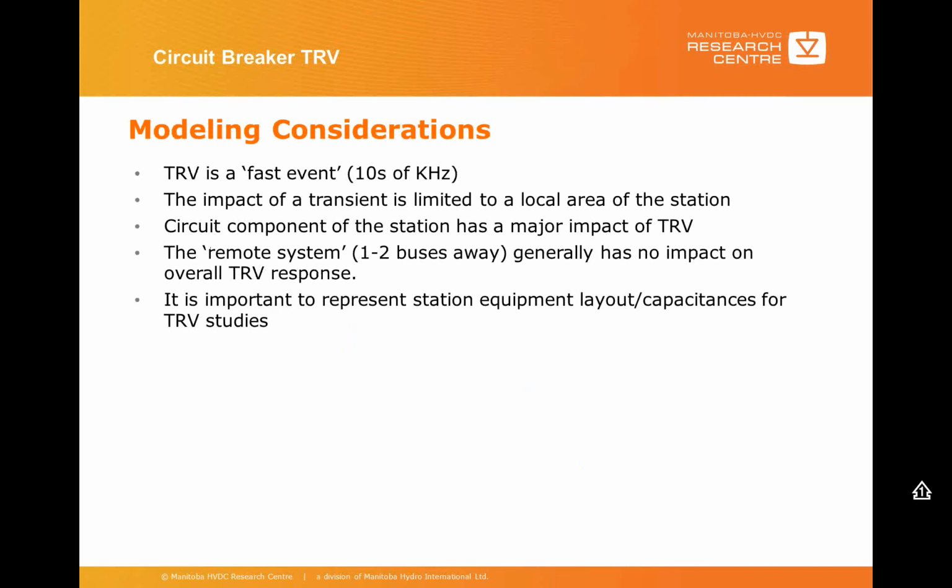Next, we will talk about modeling considerations in PSCAD once you want to do a TRV study. As you know, the TRV consists of fast events in the tens of kilohertz. So the impact of this transient is very limited to the local area around the substation, and the circuit components inside the substation have a major impact on the TRV.